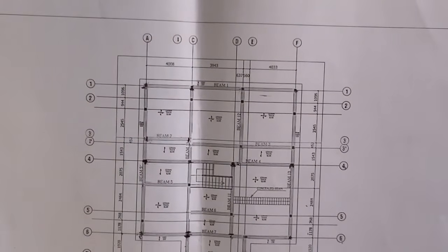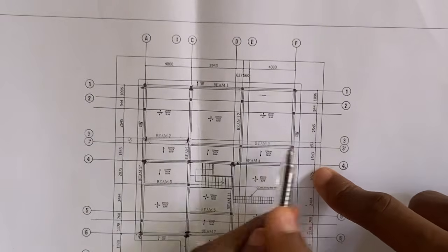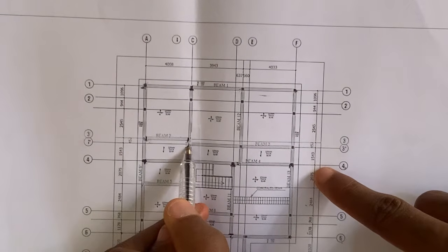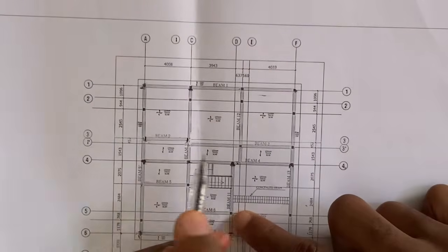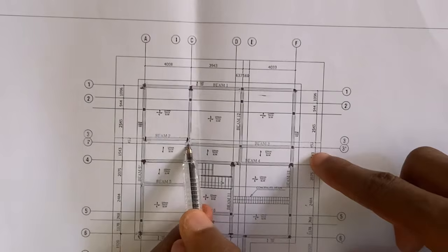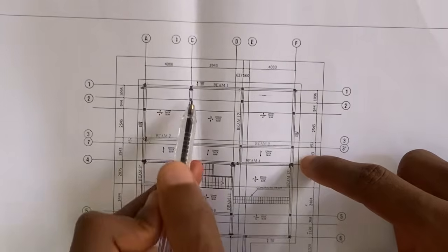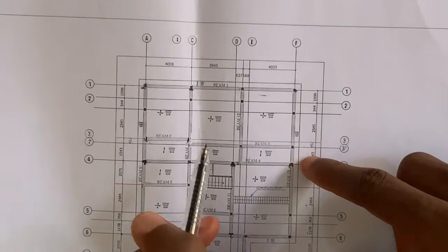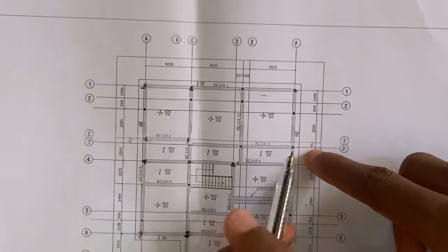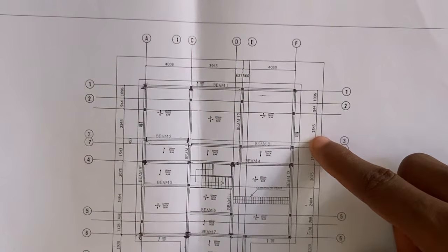So the next beam we're going to be looking at is beam 3. And beam 3 is this beam from this point here down to this point of intersection here. So now we need to determine the length from this point here down to this point. Remember that beam 3 is intersecting with beam 13, which we've already measured, and beam 10A, which is already measured. So it means that we have to minus this point of intersection from both sides to give us the in to in dimension for beam 3. I hope that makes sense.